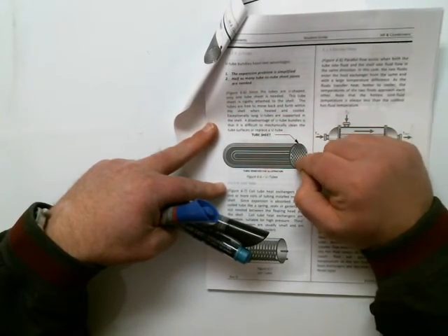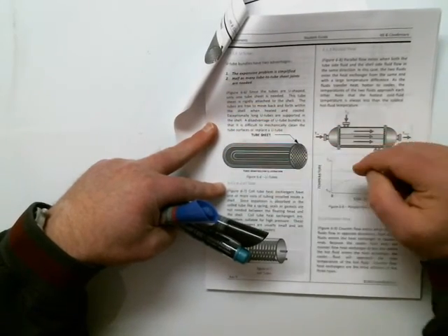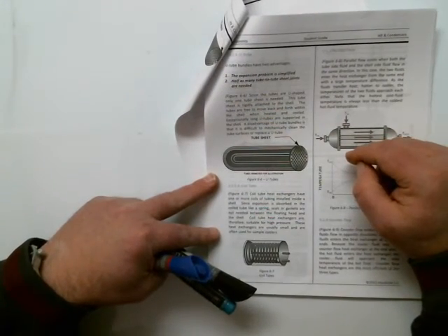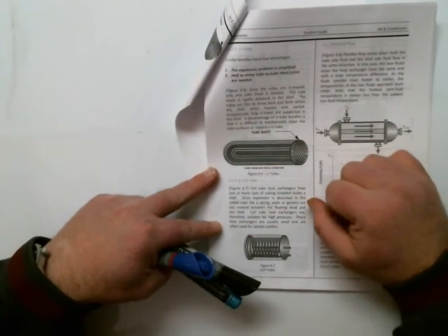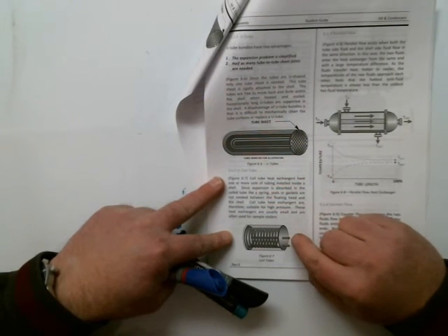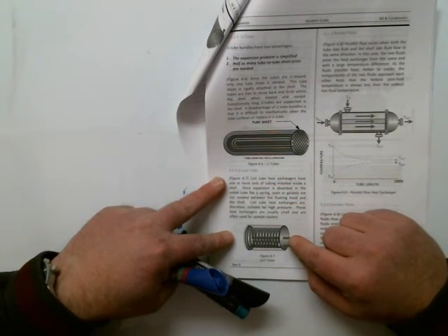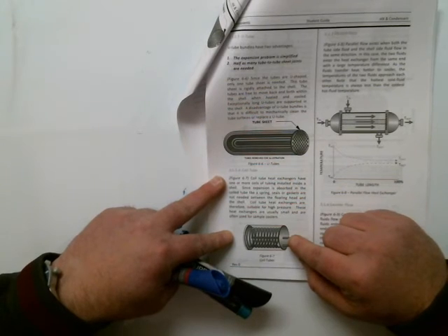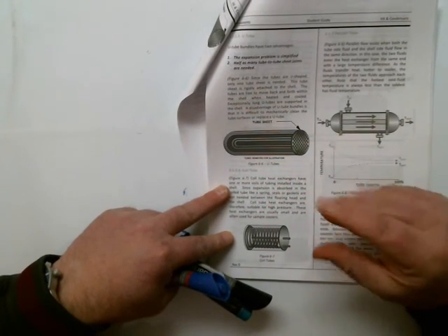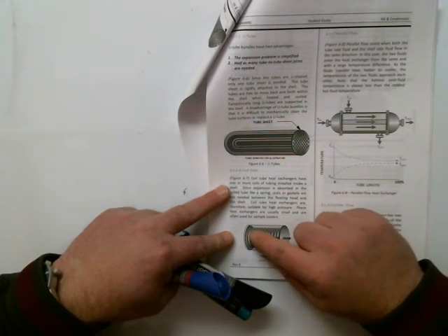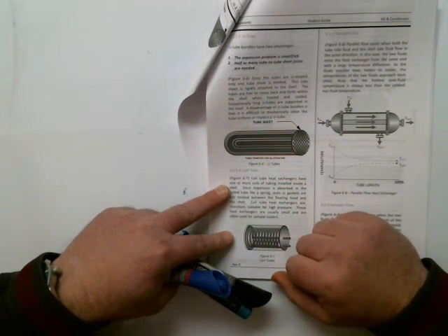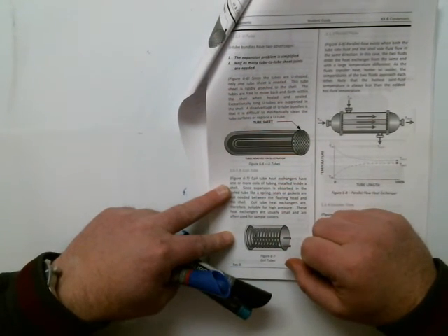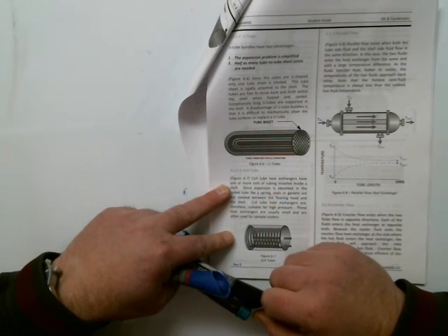The disadvantage, though, is these are a little bit harder to mechanically clean because you have to take this turn in the heat exchanger. So, in the boiling water world, we don't see a lot of these. In the pressurized water world, they have a lot more. And finally is a coil tube heat exchanger, and you can see this. This is typical of what you might see in a sample sink. It says expansion is absorbed with this floating head arrangement, so if it was heating up and cooling down, and they are suitable for high pressure environments, but they're usually small and are often used at sample sinks, and that says they're often used as sample coolers.